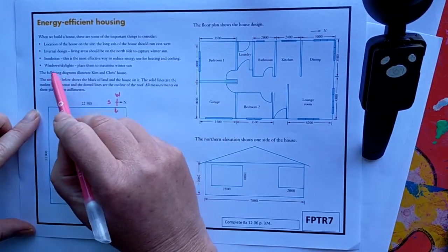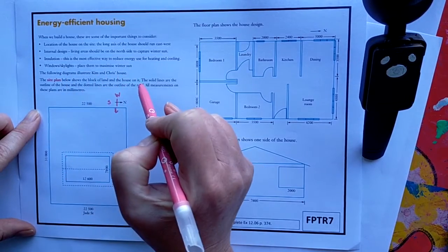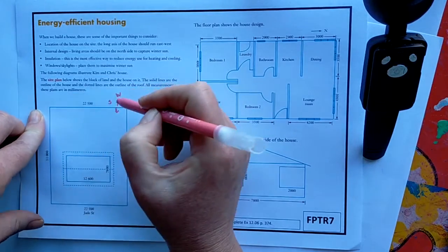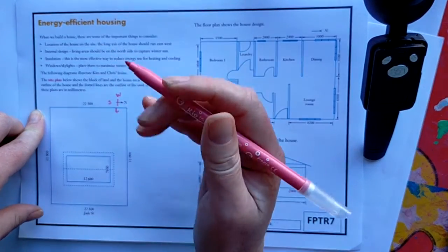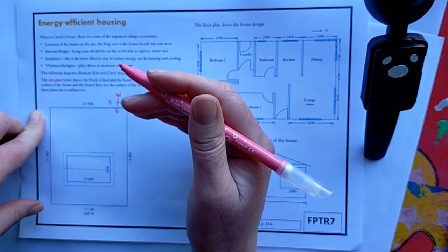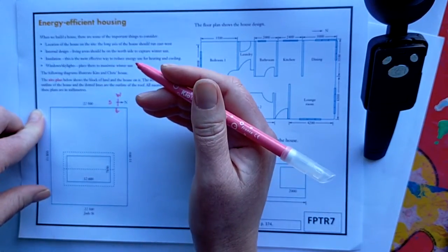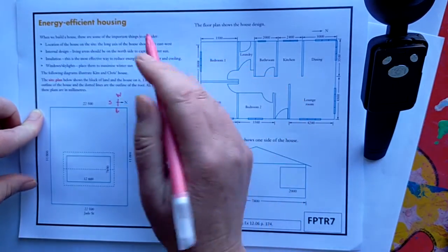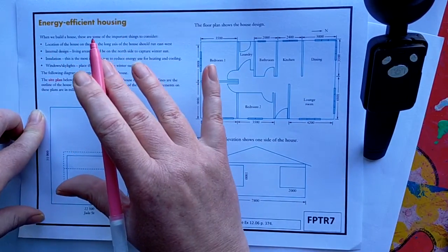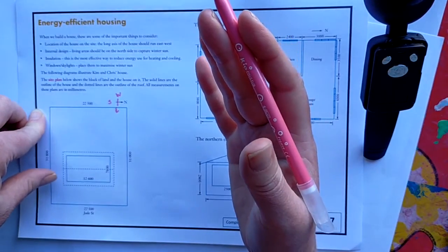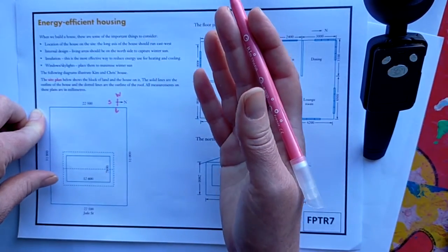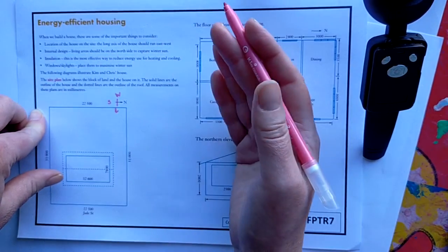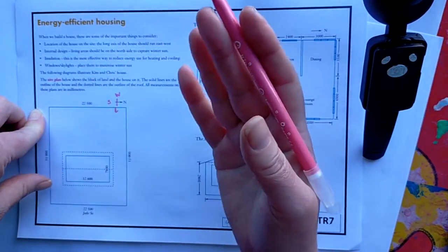And where you place your windows and your skylights is important, to maximise your winter sun. In Australia, the western side of a house gets the most sun on it in summertime, and they're the hottest rooms. So you need to think about how many windows you put on the western side of your house. If you do all of these different things, you can make energy efficient houses, and that means they cost you less money to run. So you're not paying so much money for heating or for air conditioning, and it makes them much more pleasant to live in.